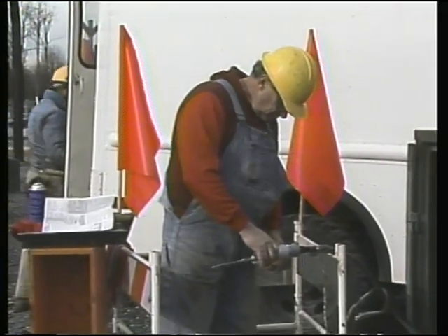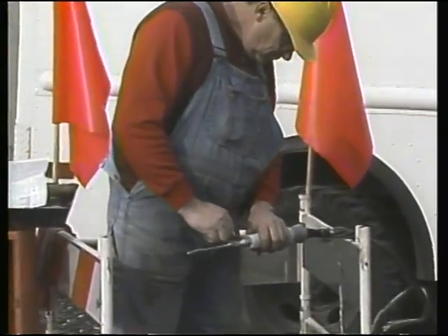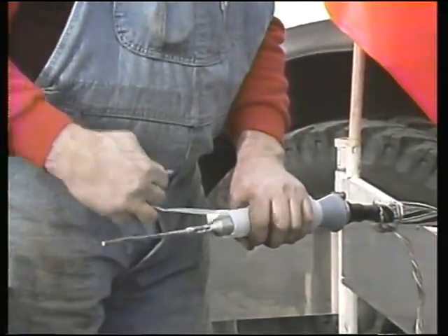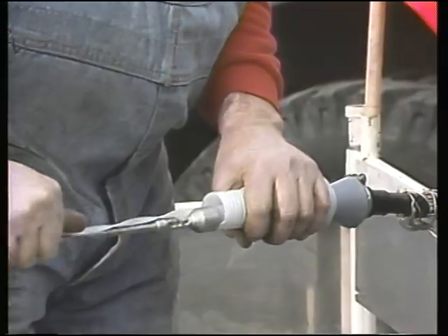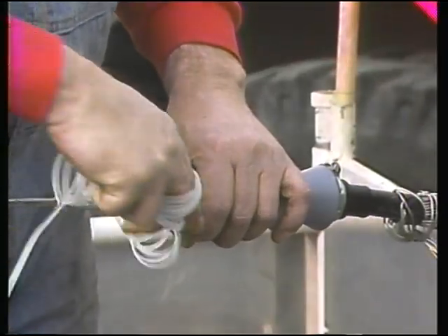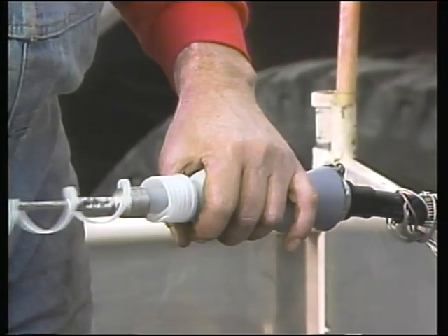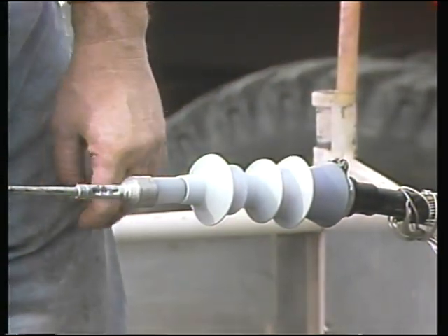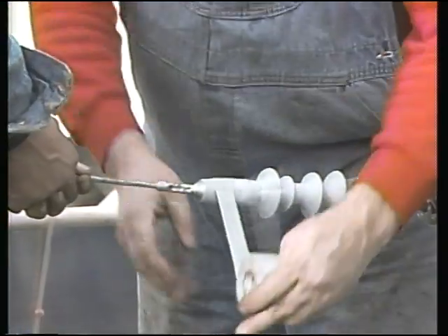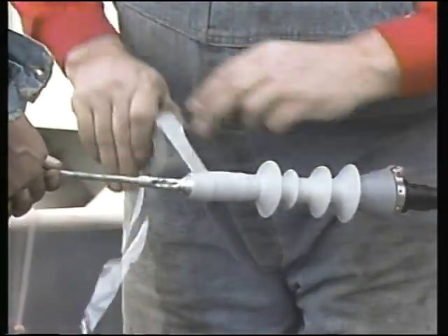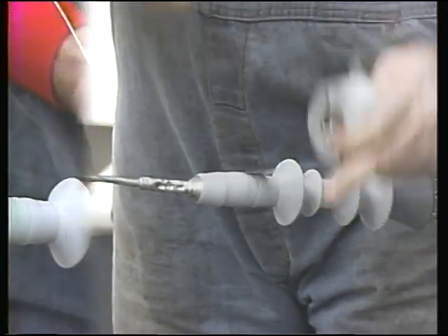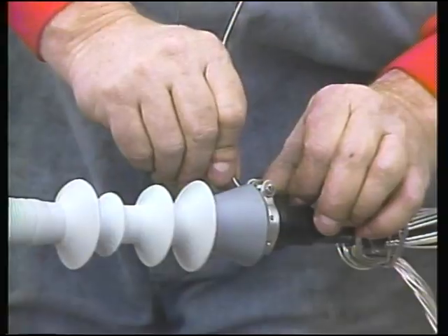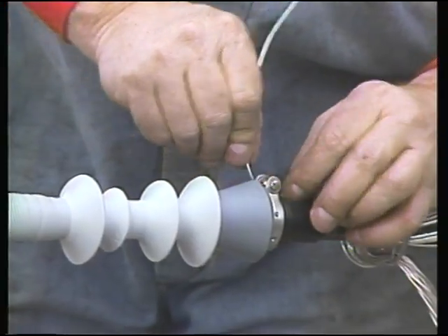The workman installs the cold shrink tube by placing it over the end of the cable so that it overlaps the stress cone. When the tube is in place, he pulls the plastic tab. The tube shrinks onto the end of the cone and onto the cable's insulation, creating a seal between the rubber insulator and the stress cone. Then the workman seals the end using a silicone tape. Finally, he attaches the concentric wires to the grounding strap to ground the termination.